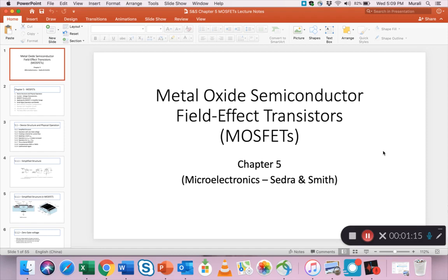Now, transistors basically have two primary functions. You may be aware of this. I may have mentioned it, hopefully, or not. But either they act as amplifiers or they act as switches. For analog circuits, the amplification property is important, and for digital circuits, the switching on and off property is important. So these MOSFETs, similar to BJTs, also possess a lot of the same characteristics.